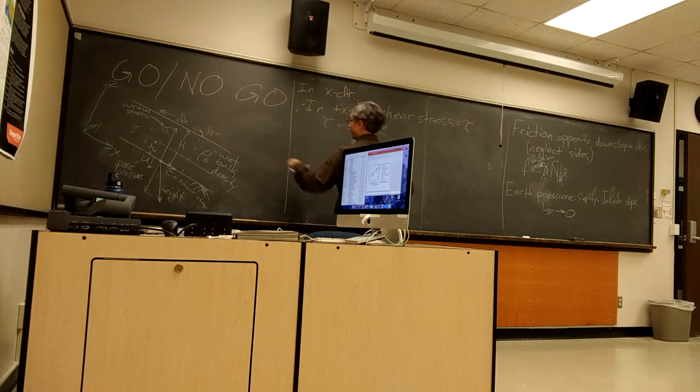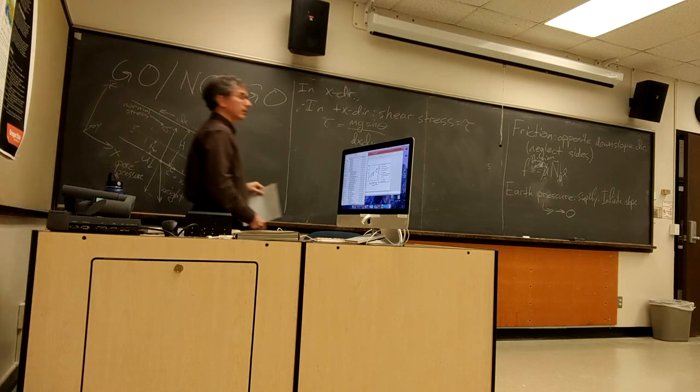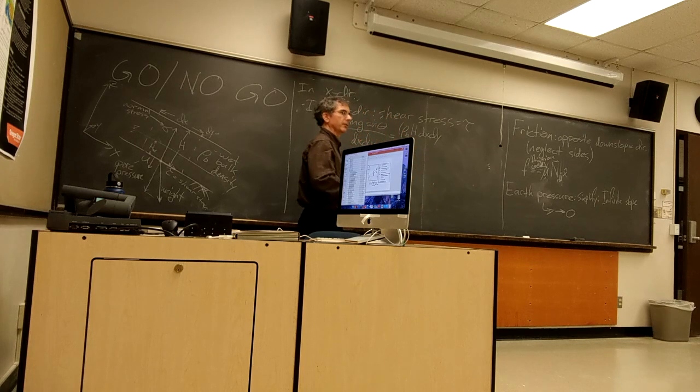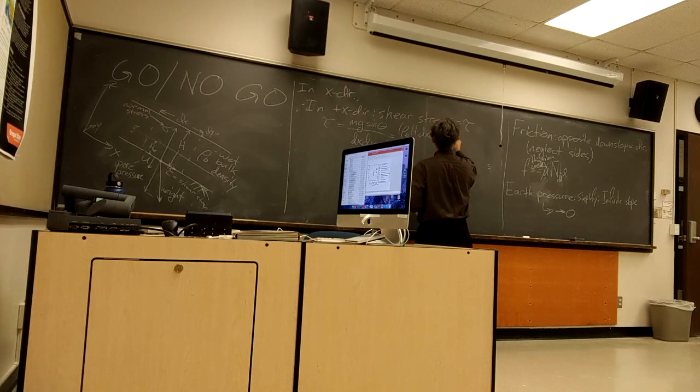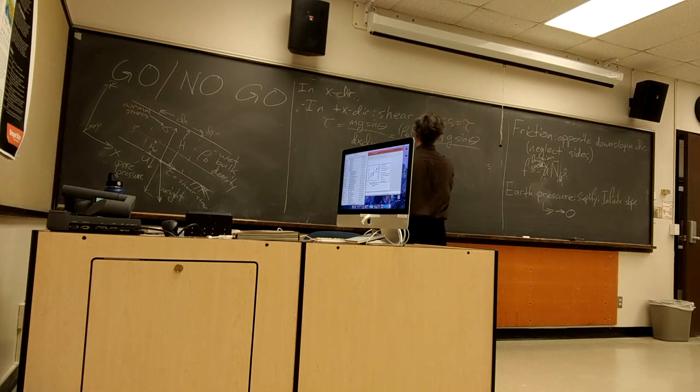My mass, now that I've written up that I've got a bulk density and I've put dimensions of this block of material, my mass is simply the wet bulk density times the depth times the dx dy. And actually I should say soil thickness rather than soil depth, just to make clear we're talking about the slope normal direction rather than a vertical depth. Again, dividing through by my dx and dy.